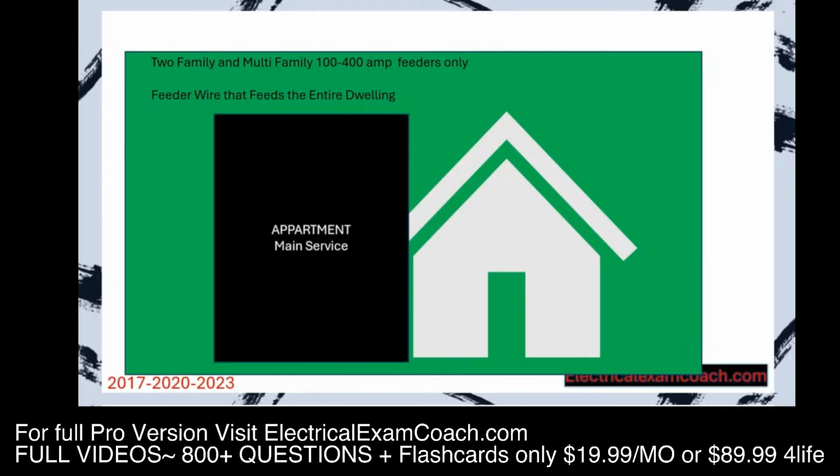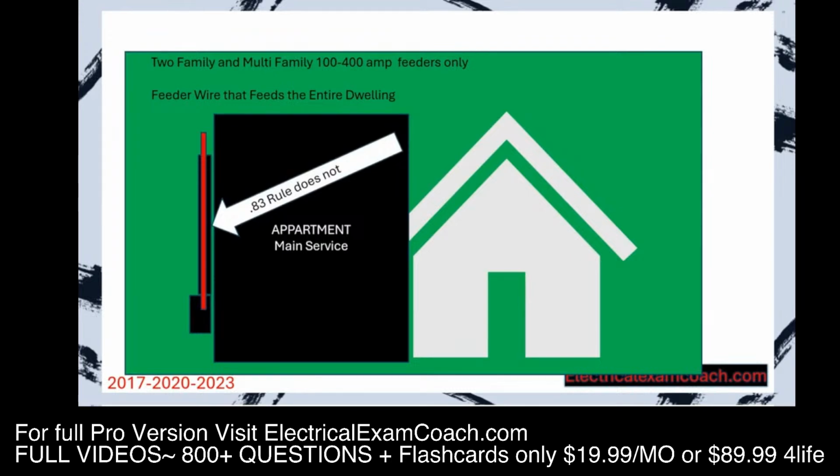That's where the main service is. Let's imagine that you have your meter center out here, you have your service riser, and then you have your wire going up. That wire there, the 83% rule does not apply. You're going to use all of the previous rules that we learned before and apply those. But the individual feeder going into that unit does. The 83% rule does apply.